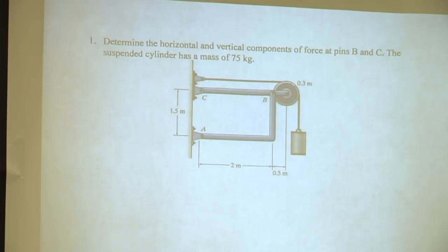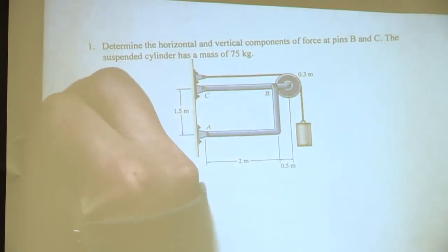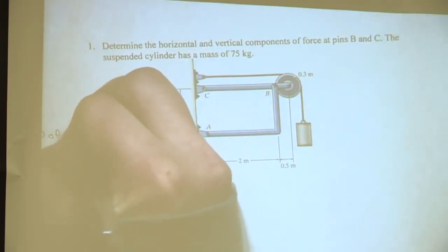Well, 3 if you consider that A, B is a two force member because of the two pins. If we look at connection A, B, we can see that is a two force member. So the two reactions that would be at B can be replaced as 1. Then how many unknowns will we have? 3, awesome. So can we solve the problem like that? Yes. So I'm going to draw the free body diagram of member BC.